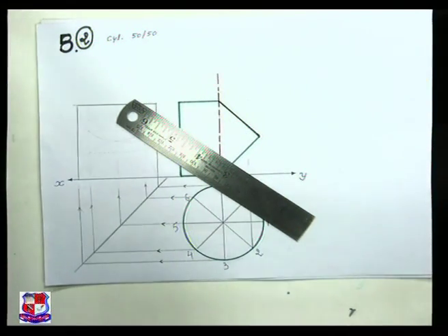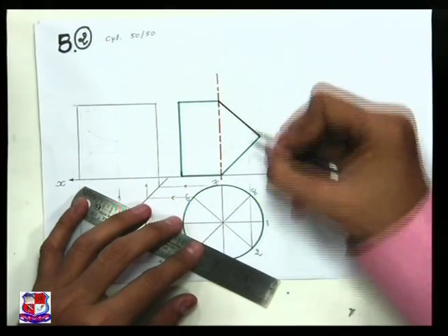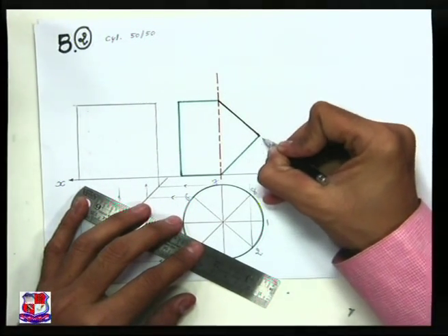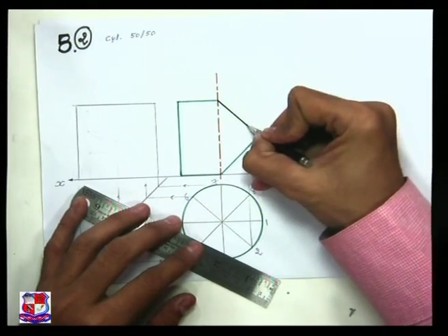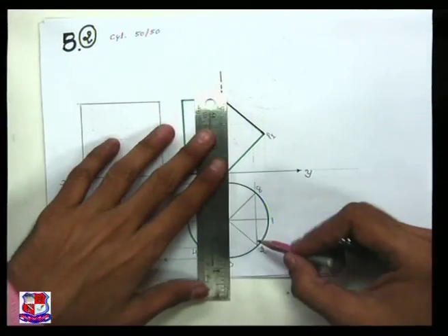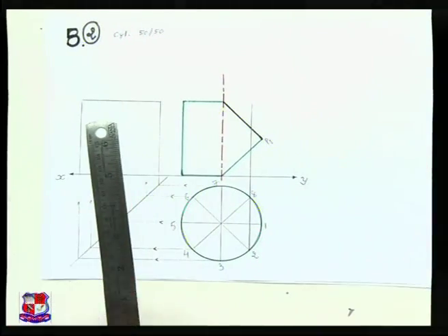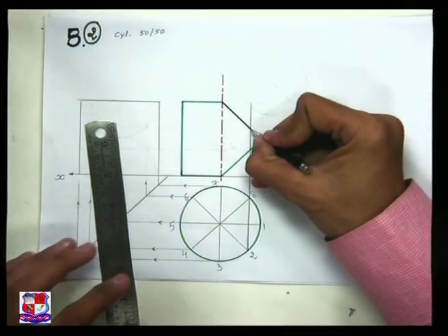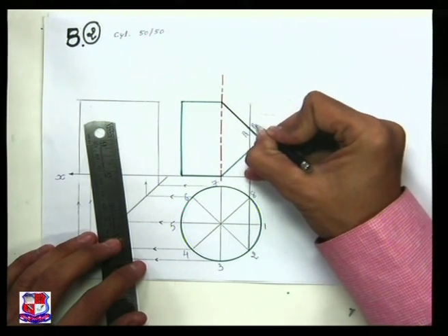So find out the points of intersection between this cutting plane and these generators. Here generator 1 is there, so point number P1 would be there. Here generator 8 is there, let me draw that generator over here also. Generator from 2 and 8, this is that generator. An intersection of this generator and cutting plane is here, so that is point number P2 and point number P8.